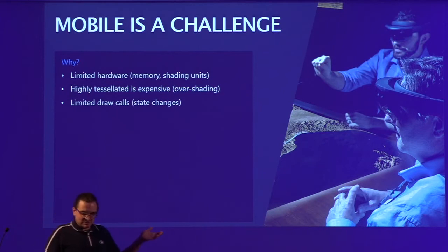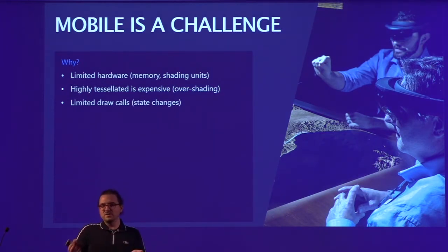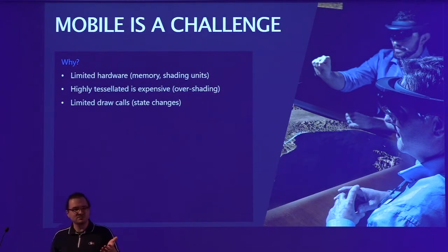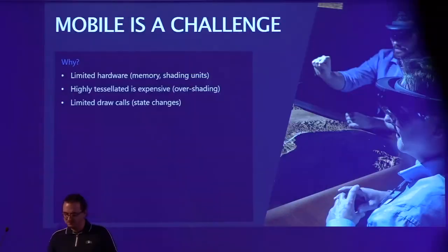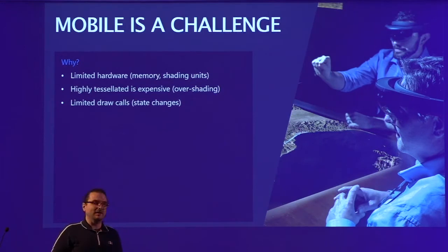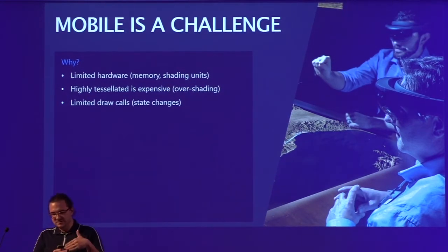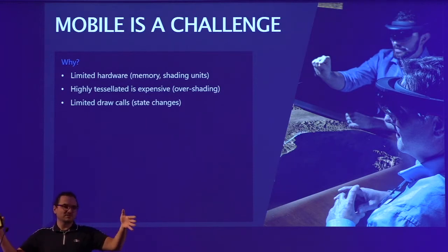Limited draw calls is another thing. It's really easy to convert a CAD format into a geometry format like an FBX or OBJ file. But the challenge is really reducing, like I said, the tessellation level, but also the hierarchy. So if you just convert that and have all those separate items, let me give you another example. Think about an architectural building, right? All those pieces could be separate in the hierarchy.